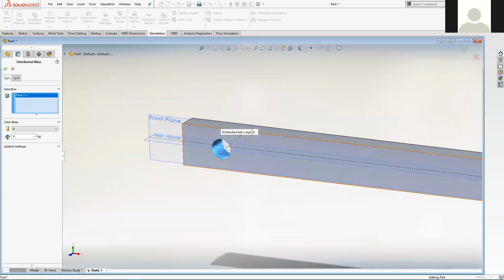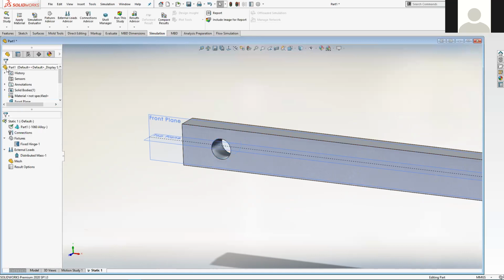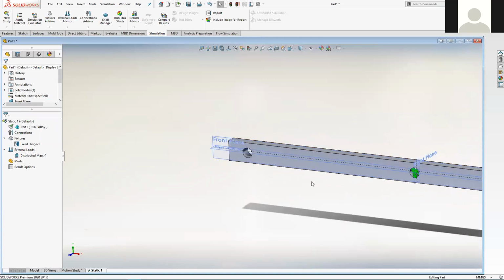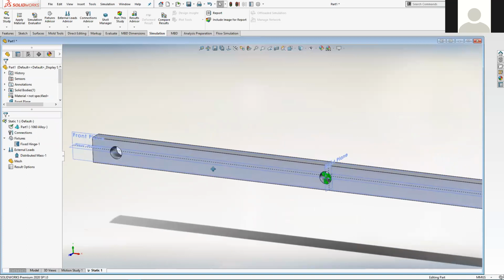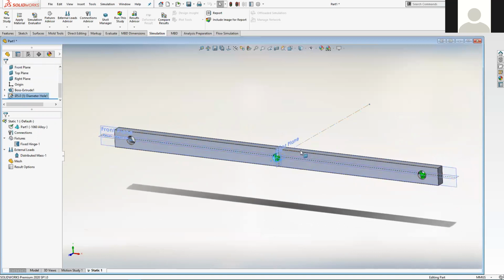I'm just looking across onto the screenshot that we're working from to get the mass. It's 4 kilos. So it's quite a modest mass that we're hanging off there. But without enacting gravity in these simulations, that mass, unless I started waving this beam around, and that mass obviously then has inertia, a resistance to move initially and then change direction, and I'm not doing that, so I'm going to have to switch gravity on in this simulation.